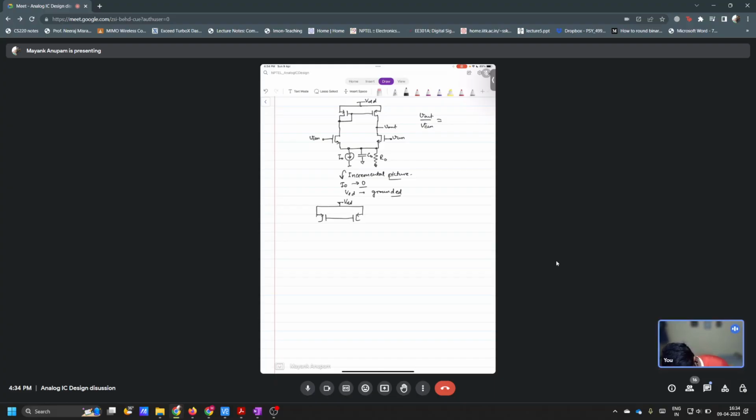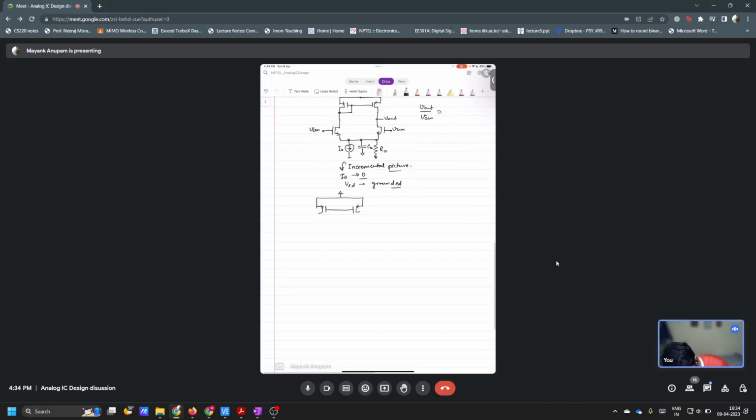Are you sure? Do you think that should happen? So what did he say? R0 and C0 should be split equally between the two branches. It is not a symmetrical circuit, right? Yes, it is not symmetrical. You see this diode connection here. You cannot draw a line here and say that these two are exactly equal to each other, because this side contains a diode connection and this side doesn't. So what should happen to R0 and C0? They should simply be here, isn't it? Yes, sir.